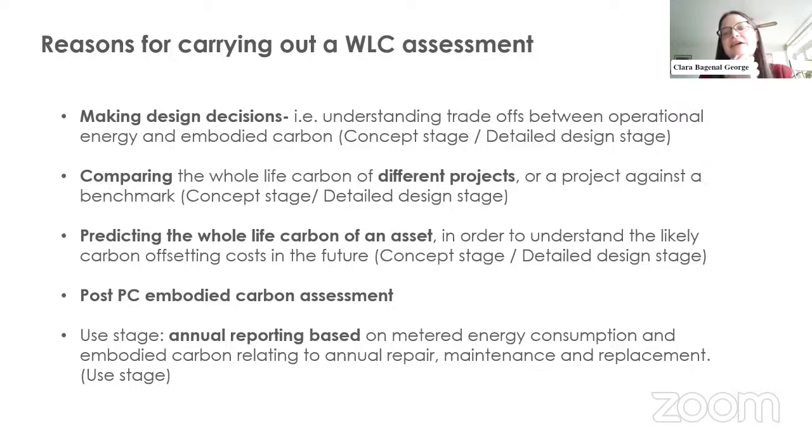You might do it for helping to inform design decisions at an early stage. So, do we add this extra pane of glass? What about mechanical ventilation? What about a different layer of insulation? What about the MEP systems? You might do it to compare the whole life carbon of different projects, or rate projects against the benchmark.